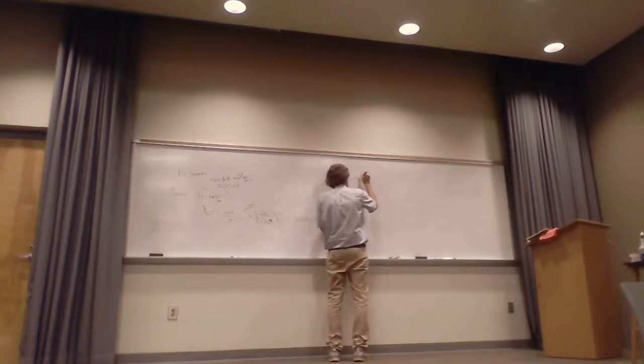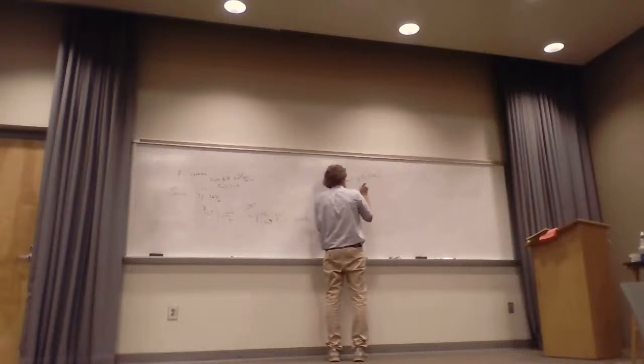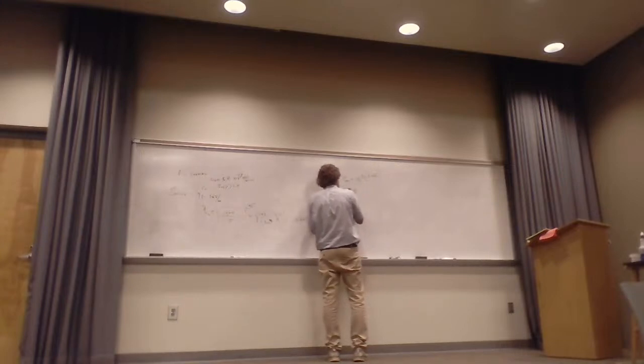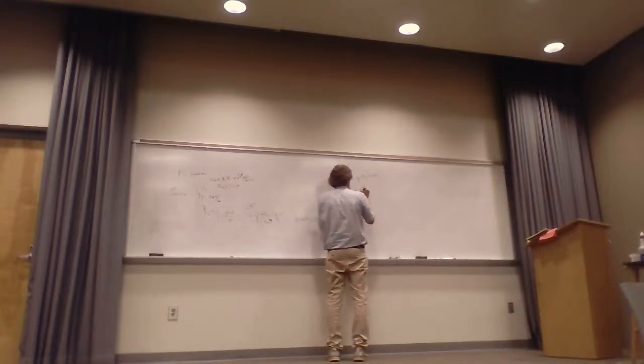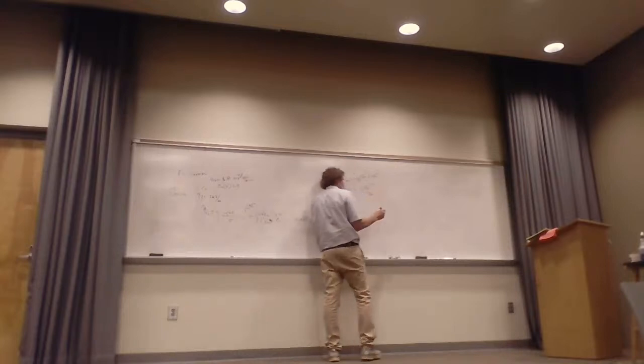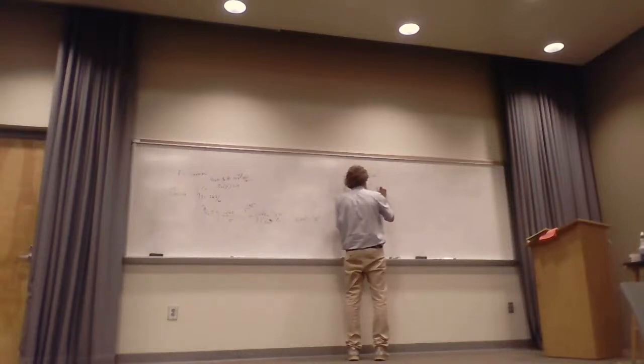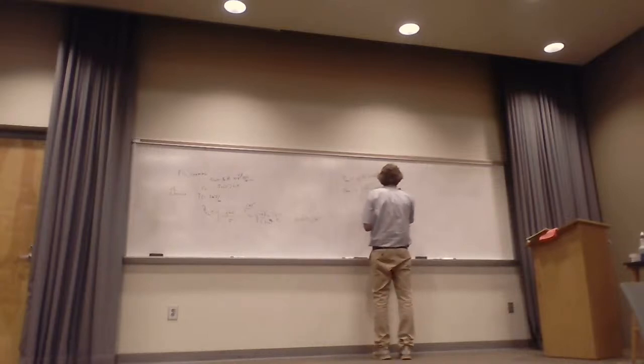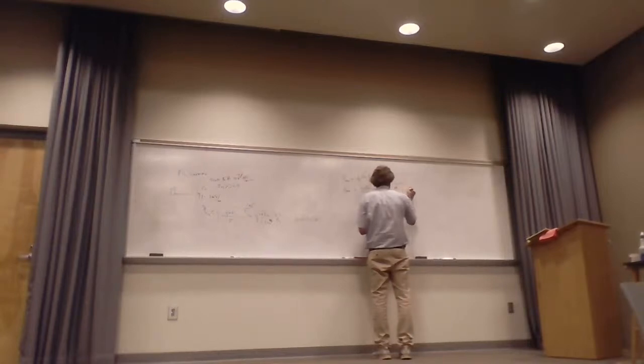Technically, it's the real part of E cross H conjugate, but for any material propagating a plane wave, it's 1/2 the magnitude of the incident field squared, divided by the magnitude of the intrinsic impedance, times the cosine of the angle of the intrinsic impedance. In this case, that's 45 degrees, and then it would be e to the minus 2 alpha z if it's propagating in the z direction.